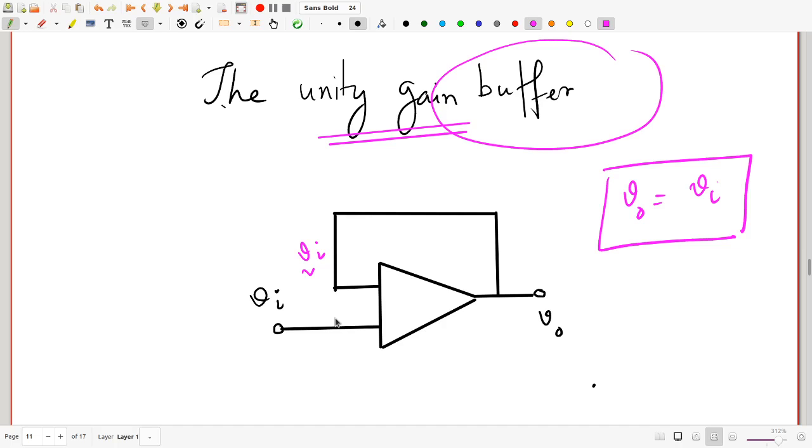Both because you're going to end up getting a smaller gain, but more importantly, you will end up getting a gain which depended on many other complicating factors like exactly how big the impedances are. Putting a unity gain buffer between two such stages means you can safely couple them.